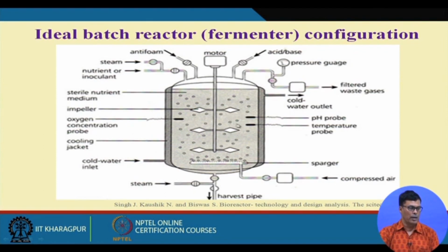In case of a laboratory, we usually recommend the small reactor. We can do this sterilization in vitro. But in case of big fermenters, usually we go for the in situ sterilization, meaning wherever the fermenter is located, there we do the sterilization. There is the steam inlet. We pass the steam, and high temperature, high pressure development takes place. With that, we maintain the temperature and sterilize as per our requirement.